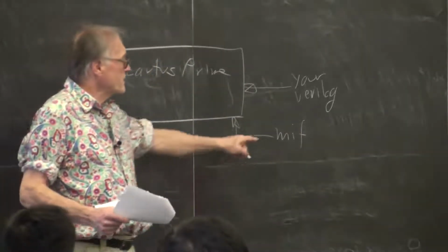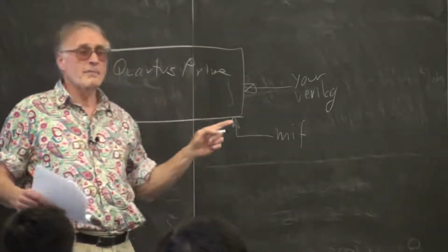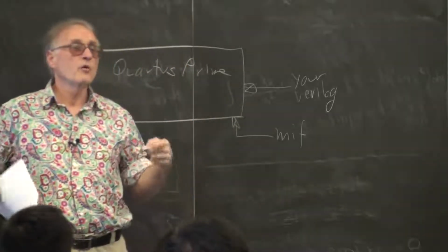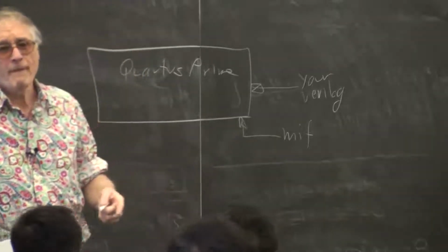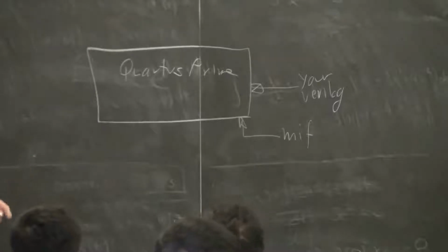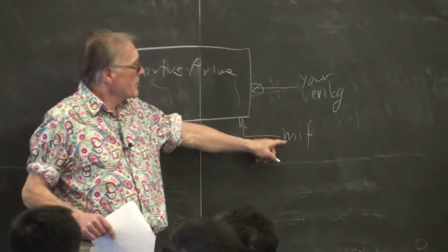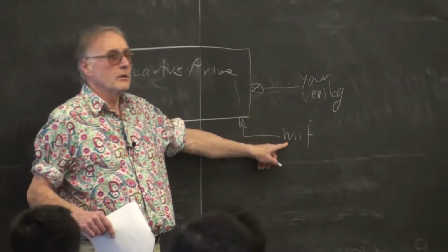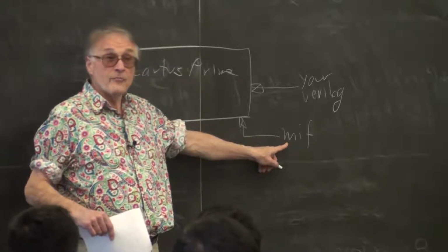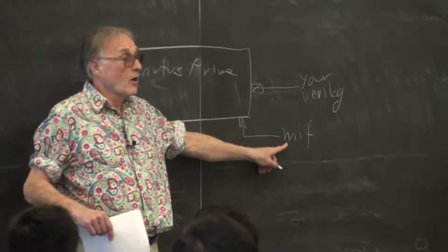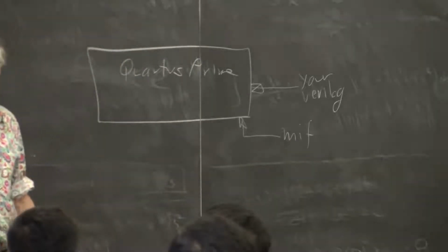Memory image files are in a format that Qsys Prime can convert into ROMs on the FPGA directly. And it's a very simple text formatted file. But this allows you to preload, say, code onto the FPGA if you're building a processor, or a ROM table if you're, say, building a direct digital synthesis unit.